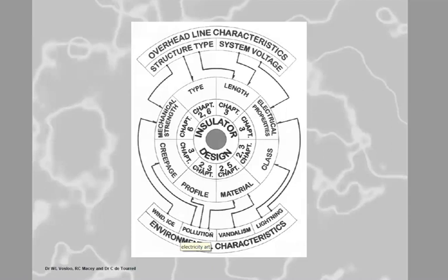Now when hydrophobicity transfer takes place, it goes into the pollution, okay? And what happens to A? It becomes smaller, smaller, smaller until it nearly disappears, and that's why current goes down. And rho is the resistivity of the pollution layer. As it migrates into the pollution layer, what happens to rho? It becomes bigger, bigger, bigger rho, bigger R, smaller I. Insulated pollution, explained, done. Rho L over A. I can solve any in-service problem you've got with pollution with R equals rho L over A. And that's it, as simple as that.